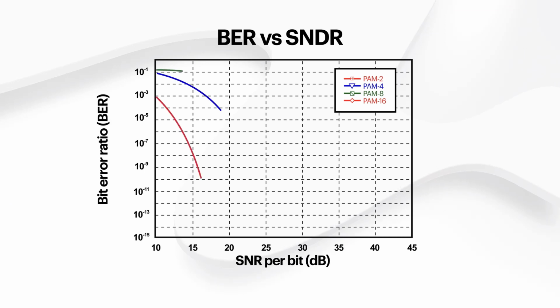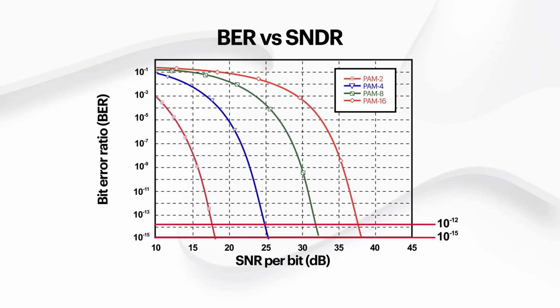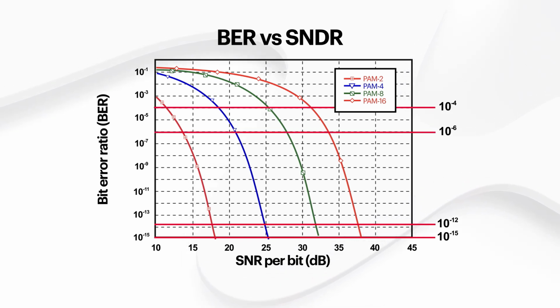So the fundamental data error rate we're shooting for is no longer 1e-12 or 1e-15, but maybe 1e-4, or in some cases 1e-6, in some cases as low as 1e-2. But error-free transmission is no longer the goal that we require, at least without the forward error correction, the FEC coding.